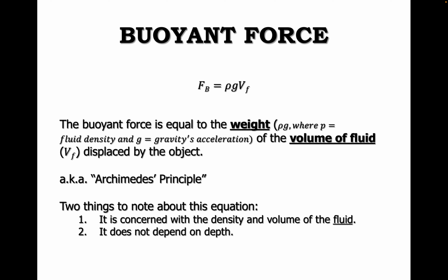You might see this in a bathtub. If you sit down in a bathtub of water, the water level will actually rise. That's because your body displaces some of that fluid. So that's what we're talking about here in VF, the volume of the fluid being displaced by the object in that fluid. So buoyancy force is also otherwise known as Archimedes' principle. And what's important to note about this equation is it's concerned with the density of the fluid and the volume of the fluid. However, it does not depend on the depth of the object in the fluid.